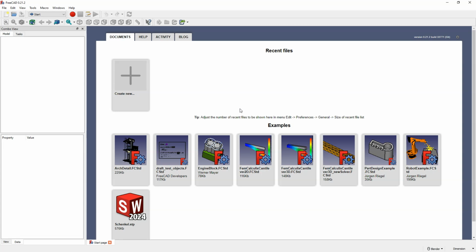Moreover, FreeCAD, in addition to 3D modeling capabilities, also allows us to prepare machining programs for basic 2D milling operations. That is, here we can prepare machining programs for CNC milling machines for operations such as pocket machining, contour machining, drilling or hole machining. Also, when it comes to FreeCAD's capabilities, they are really big, and juxtaposing this with the fact that it is a fully free system, we get a really powerful tool completely for free.